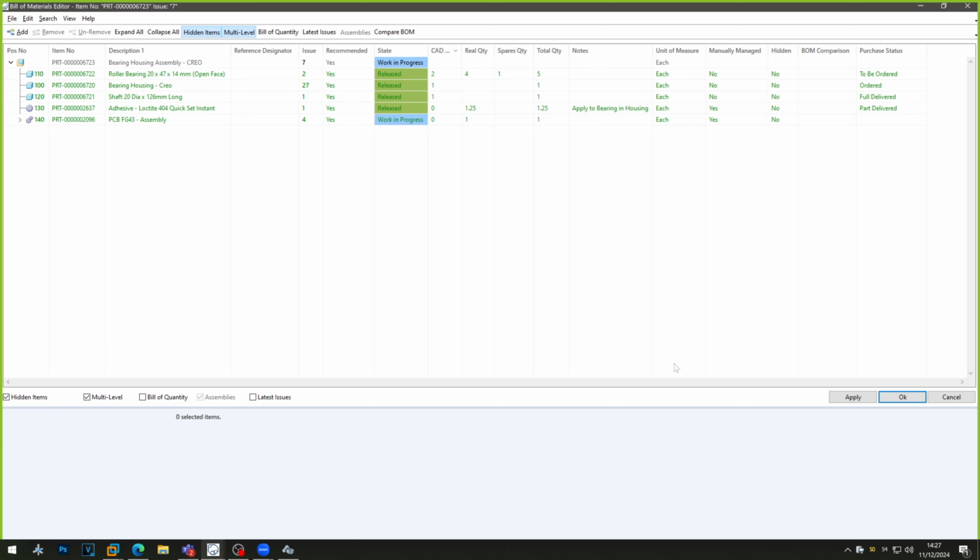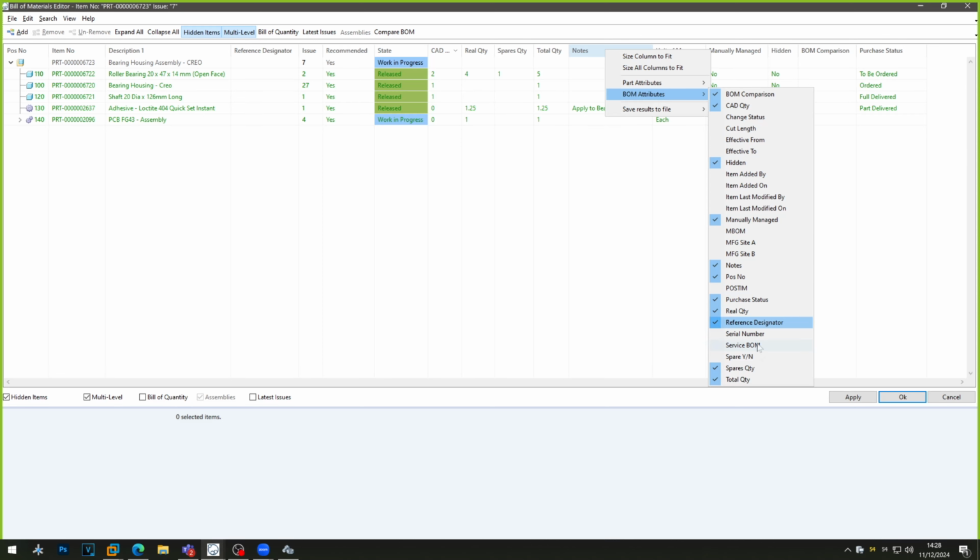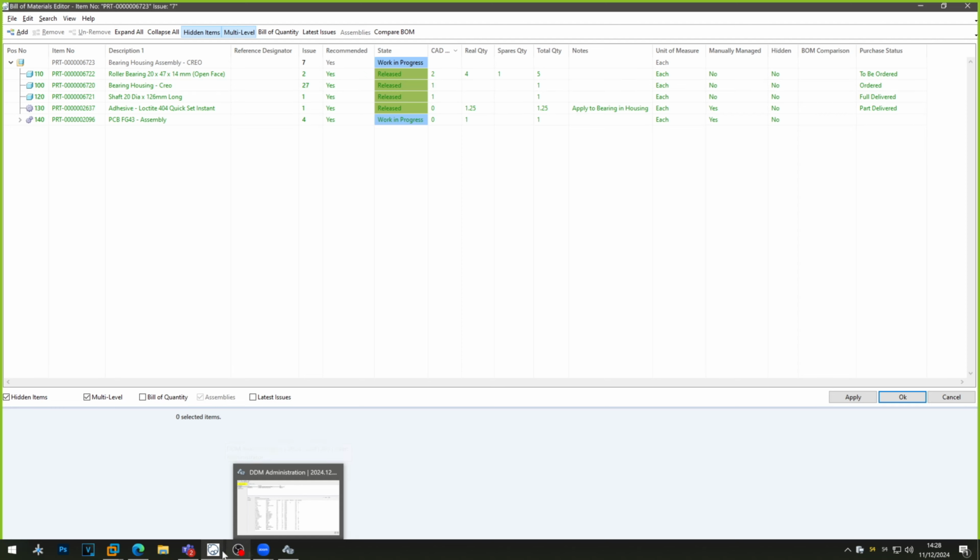So just to give us an understanding of that kind of information against a bill of materials if you don't run an ERP system. And it's quite common these days. Bigger manufacturing companies typically always have ERP, and you would do that in an ERP system. But for people who don't, it can be quite useful. Okay, so the difference between part and BOM level attributes, they can be really quite useful. Effectivity dates, effective from, effective to, cut length. You might have an item on there that's a raw material, but you want to specify the cut length. There's lots of examples where you might want to use those things.